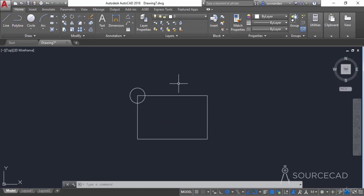For that, we can select the move tool from the modify panel. So select the move tool. Now click on the circle, press enter, and now specify the base point. As you can see here, the command line prompts you to specify the base point. So the base point will be the point from where the object will be picked.